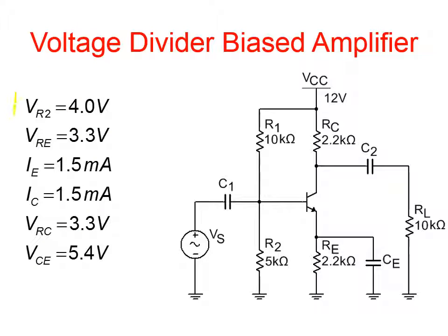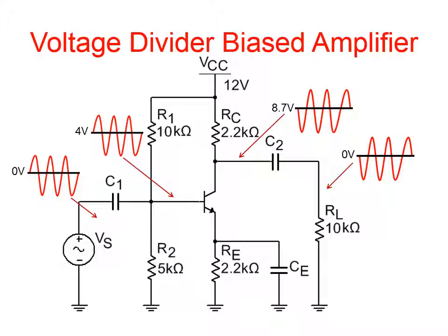So here's all the quantities we've been able to find so far. Our circuit. So going back now, when you apply your AC voltage on top of this, all of these voltages ride on top of what those DC voltages are. So remember, that's the purpose of C1 and C2 here. Those are coupling capacitors. And you get the output coming out. So input here, output over here.